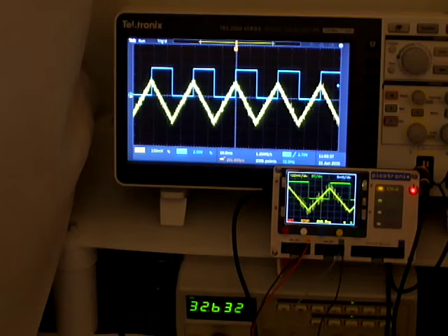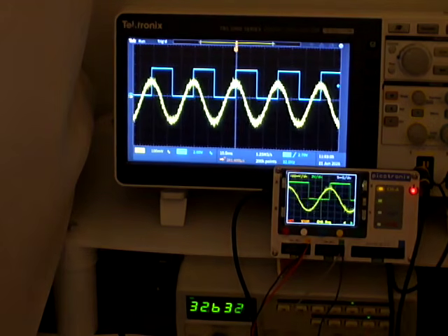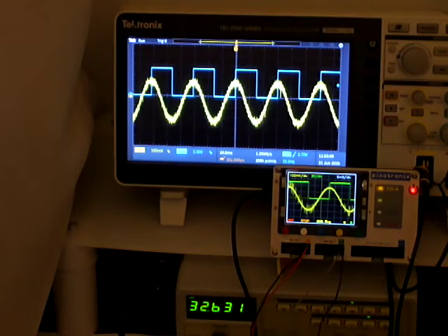So another point to note there is that the ADC in the 2350 is quite happy. We're using 200 steps of its 4096 steps. So we're only using 5% of its total range to track that triangle wave, and the quality of the triangle wave when it's averaged is very good. So we can switch to a sine wave to check that. Same thing.